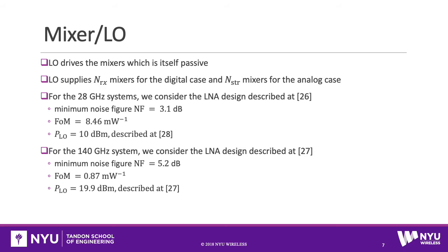In our analysis, we consider the mixer as a passive device. As a result, the power drawn by the mixer is by the LO generation network. In our analysis, the LO supplies NRX mixers in the digital case and NSTR mixers for the analog case.